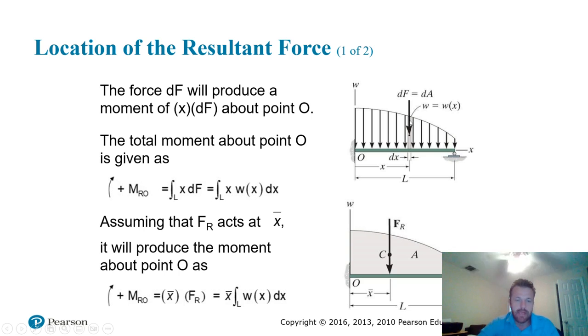So if you think about what we have here, we have an expression for the total rotation that the distributed load will cause about point O. However, what we're interested in is making sure that that's the same as the setup that we have for our equivalent single force. The book makes this a little bit complicated here. This integral of w(x) dx from 0 to L, that's just them talking about the entire area under this curve. Remember that the entire area under the curve is the magnitude of the force.